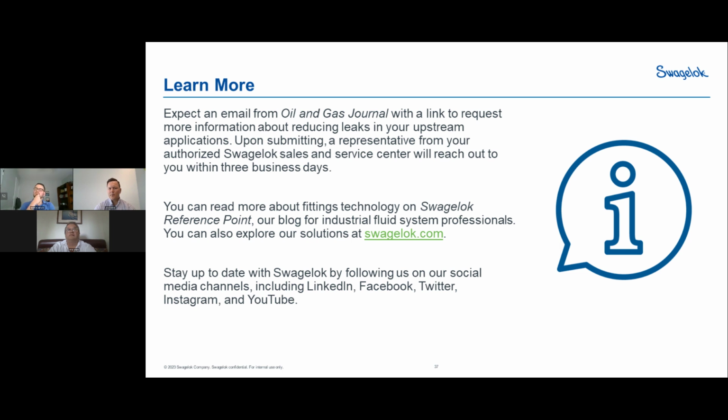And then in terms of materials, there's a couple of things to think about. One is, obviously make sure whatever clamp material you're using plays nice with the tubing material. But then also think through any of those entrapment areas that could exist with a tubing clamp. If there is an area where anything in the environment could collect and settle and maintain itself against that tubing, you could end up actually with not a vibration concern, but more of a corrosion concern.